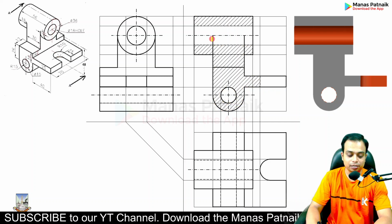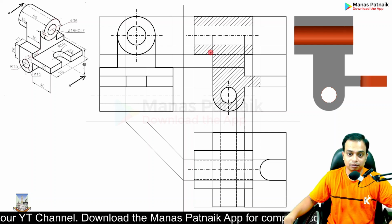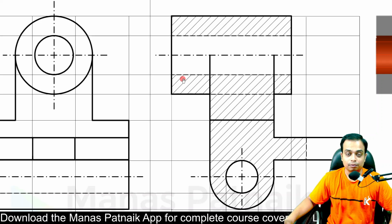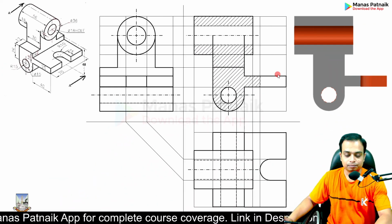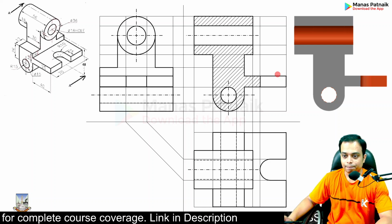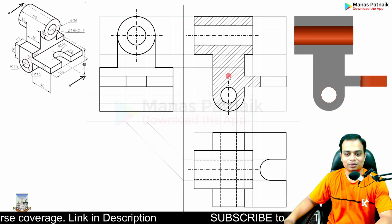And when you do the hatching, please everybody note that these solid lines have to be removed, because they were part of the front view. You are making the section view. Even these hidden lines, remove them. This is how the diagram would look finally. And want to see some magic? Let me bring this over to this side.